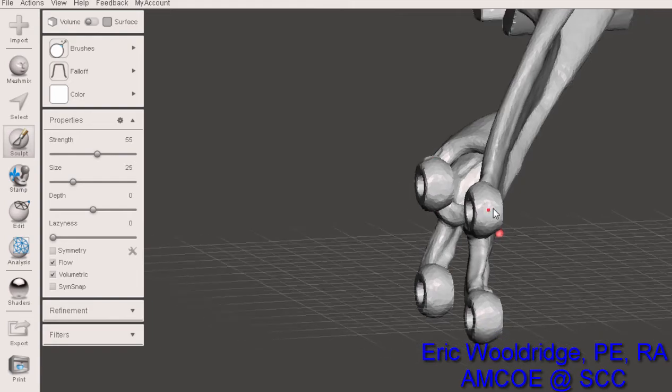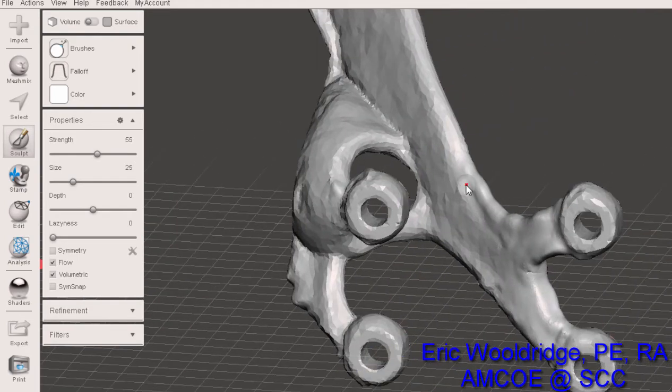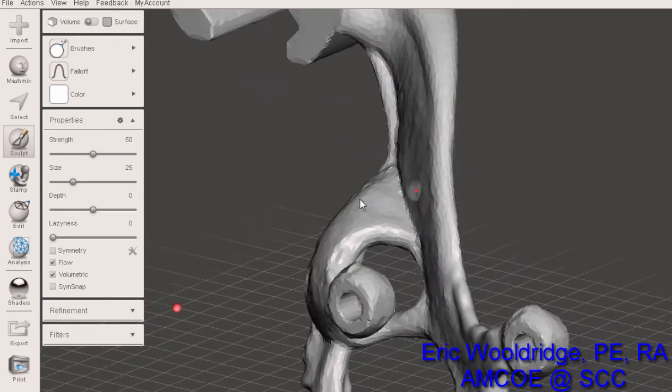One of the phenomena associated with additive and the way the slicers work is that ridges work really, really well for strength, but not big fat ridges. You want ridges that are kind of small, because that way it creates a bump out as far as the printer is concerned, and creates the tight little ridge. So thin ridges are actually better than big thick ridges.